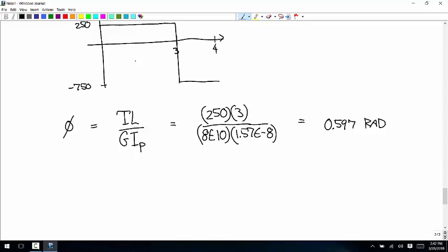What that says is it goes through an angle of like 35 degrees or something. 34.2, yeah. 34.2 degrees is the angle of twist right where that external load is applied. And then it goes back to an angle of twist of 0 at the 2 attachment points.